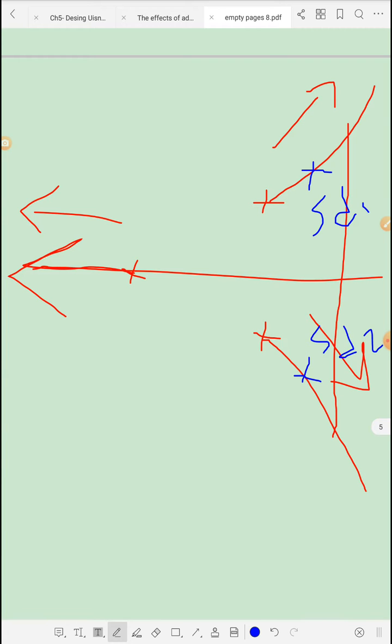If it lies on the root locus, then as we have covered in our previous chapter, this means that the angle condition is satisfied, since all the points on the root locus satisfy the angle condition. Our design process will only be to apply the magnitude condition in order to find what value of K makes this one of the pair of roots our desired location.